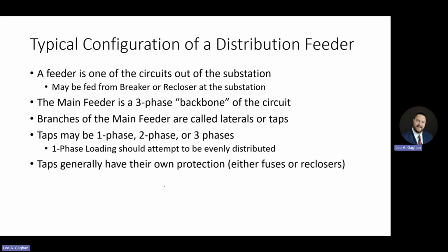The main feeder is a three-phase backbone of the service. There may be taps that come off of that backbone. That may be single phase, two-phase, or three-phase. If you have the one-phase loading, you should attempt to evenly distribute that single-phase loading.